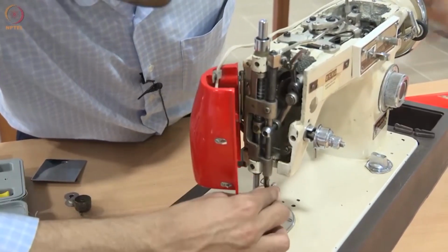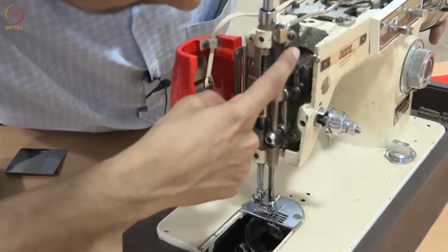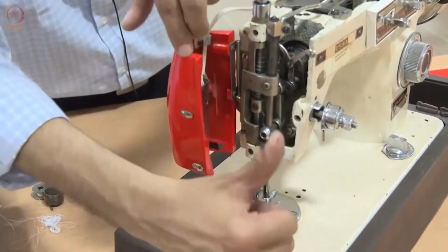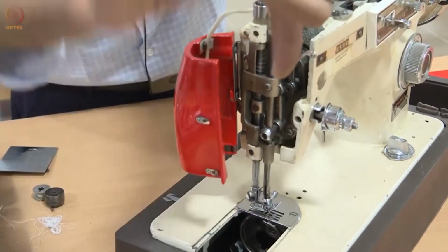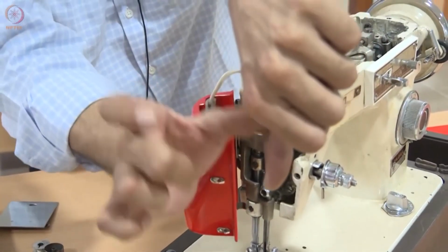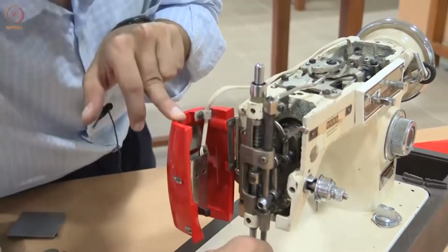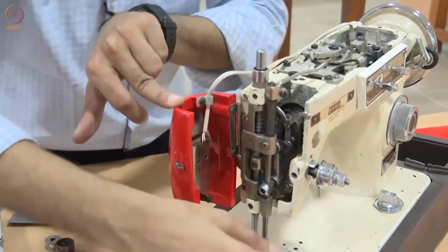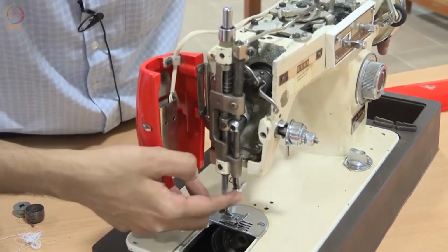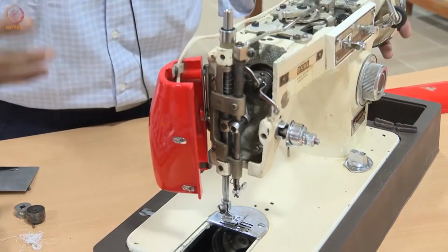So anytime they become all inline, I cannot give the input and get the output, because the force that I apply and the crank are all aligned in a single straight line. Since I don't have any lever, I cannot produce a torque. Basically, the mechanism is said to be in a state of singularity, or a state of toggle point.